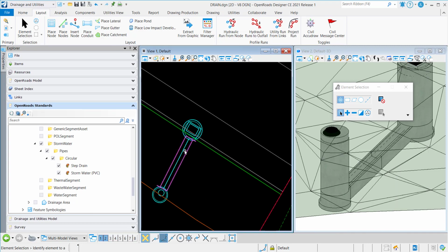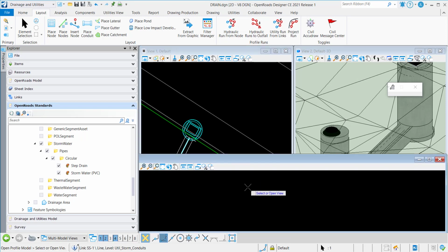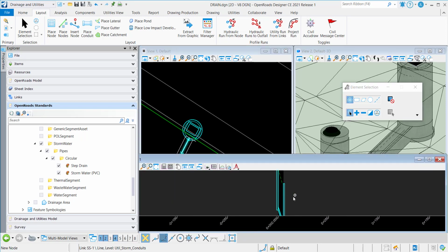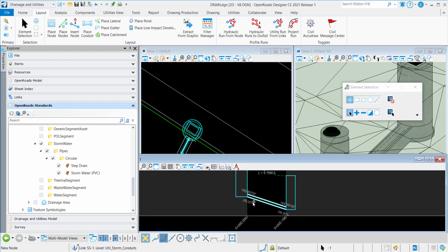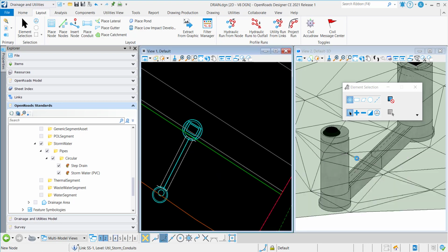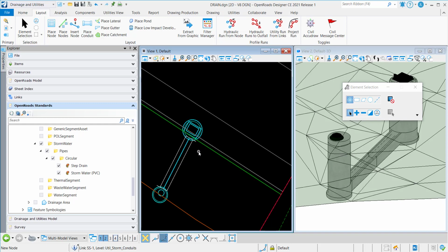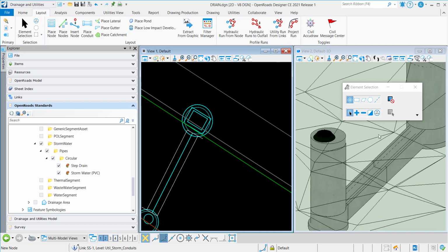So what you can do now is based on what we call corridor modeling's capability. First of all, I will check the slope here. If you go to the profile, you can see the slope that I can provide to you. So it's about minus 30 degrees. If my step is going to go to 0.5 meters, it should be going back to about 150 mm here. So it will create a step here for me.